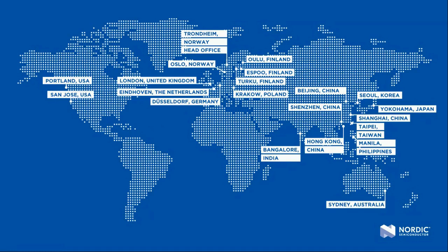There is a question if power management is integrated inside the 9160, and the answer to that is yes. There's a complete power management IC inside the 9160. You don't need any external power management ICs as long as you respect the maximum input power of 4.5 volt or 5 volt for the 9160. There's a question on which RTOS is used. As mentioned in the presentation, we use Zephyr, which is quite recently developed, but a very powerful open source RTOS.